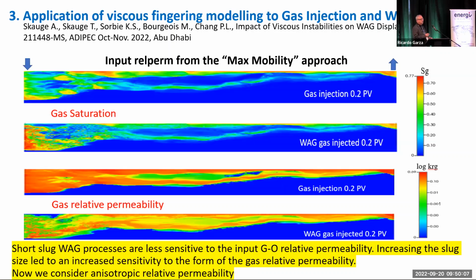gas. Water is then stopping it up and trapping some gas, and the new gas cycle will not be able to transport for a long time before we are changing back again to water. And thereby we have discontinuity in the gas phase with the very short slugs.